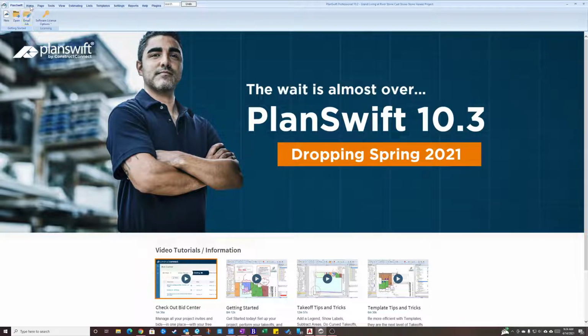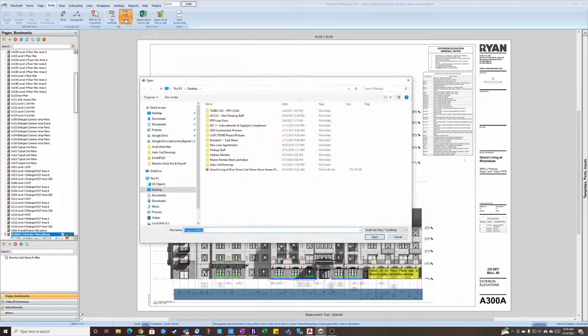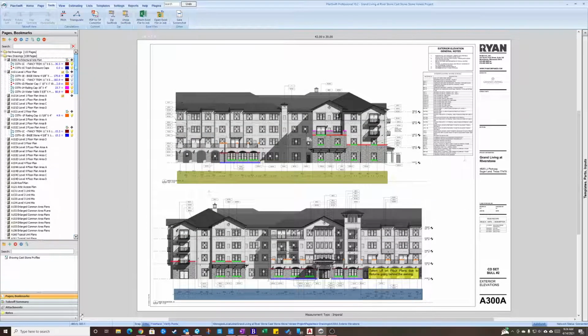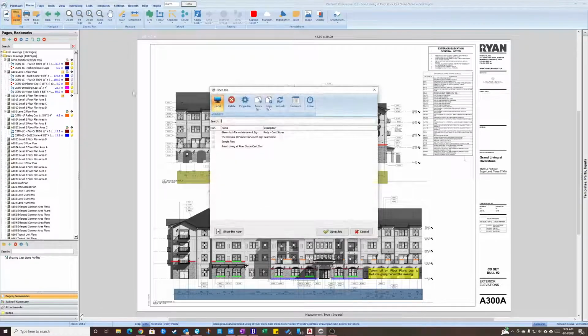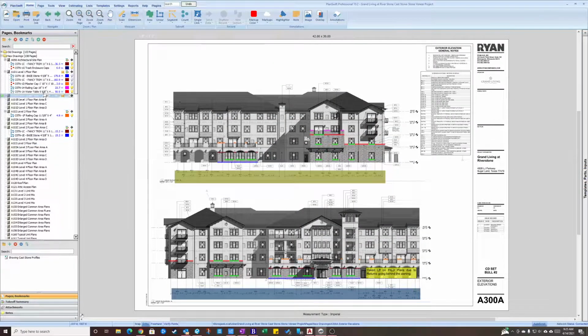So what you're going to do is the same thing. This is on your computer now, okay? So you're going to go to Tools, you're going to go to Unzip Swift Job. And you're going to find that file that you copied to your desktop. You're going to click Open. That's going to unzip it and load it into PlanSwift, all right? And that way, from now on, it's literally going to be permanently loaded into your database. So when you click on Open, it's going to be listed here in the list of jobs locally on your computer. All right, so what's the first step?